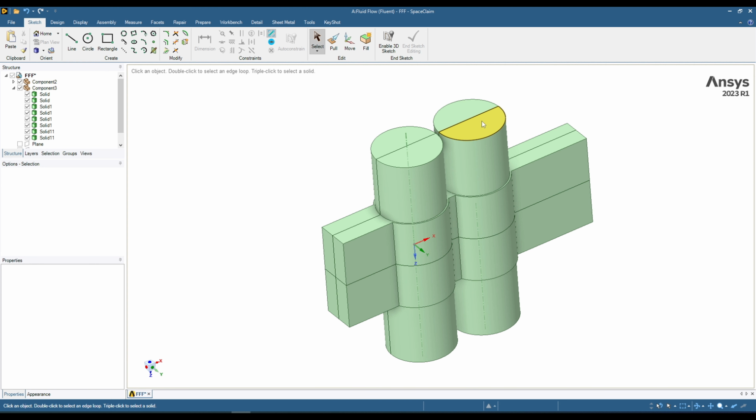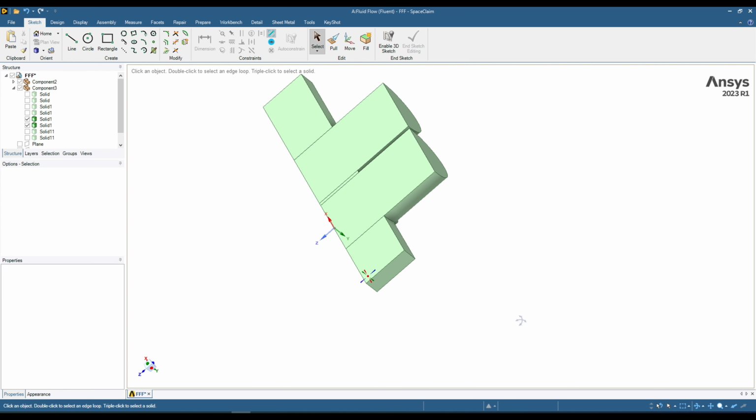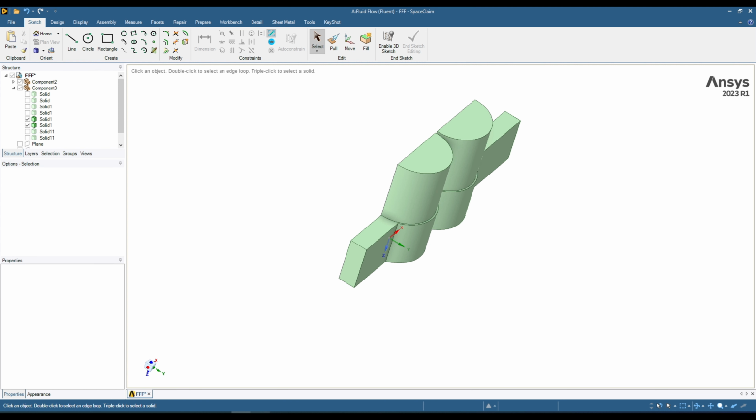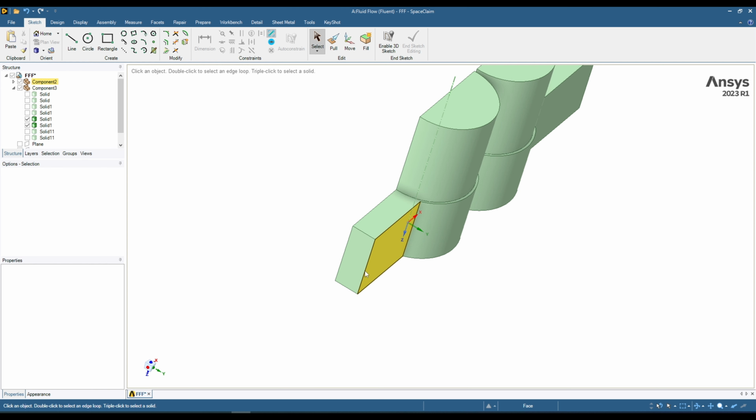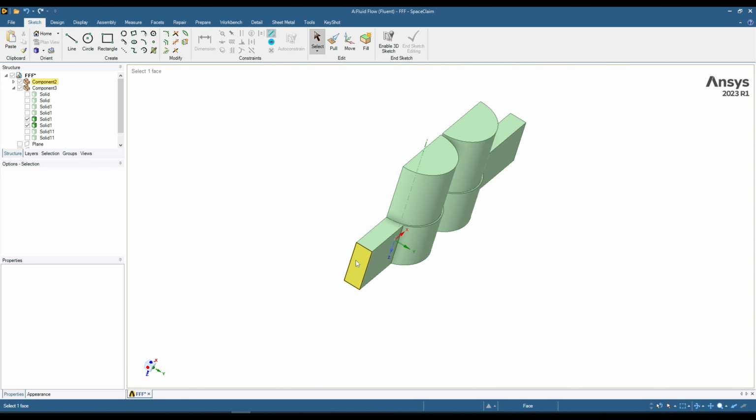So I have cut this geometry from the center and also from here. So it means we will be simulating only this much portion, 1/4. And as I said, through each module 4 gram per second flow rate would be flowing. So through 1/4 we will have a flow rate of 1 gram per second. So now let's continue with our expression.